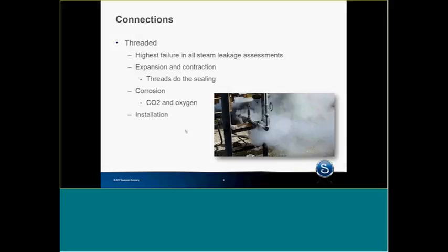I do not thread pipe. I cannot afford to have steam leaks on the project I'm doing. I can't afford to put the pipe fitters back in there to correct steam leaks or condensate leakage. So I just don't thread pipe. If you go in and have steam leaks, it's typically around the threaded connections.